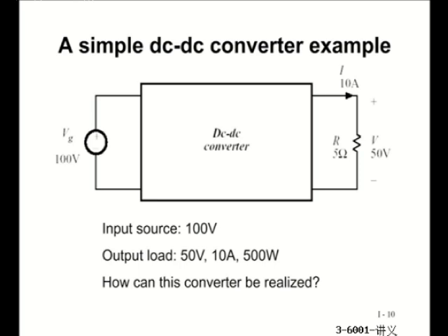They require a specific voltage level to run correctly. Therefore, there is a power converter between the battery and the IC chips to make sure the output voltage is really what you expect for the IC chips.